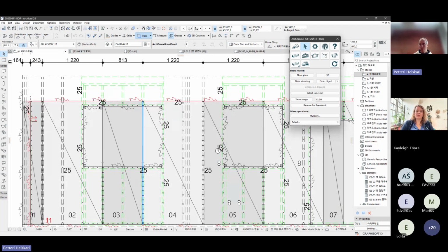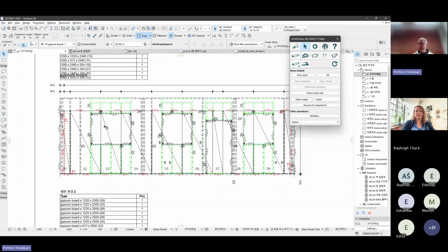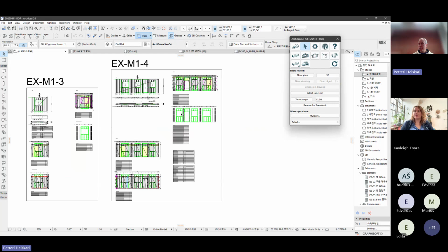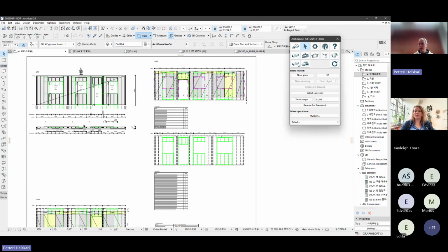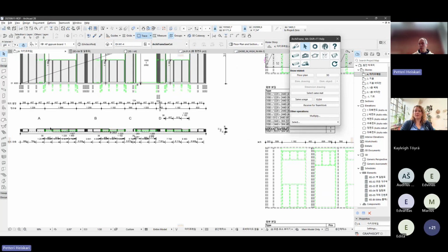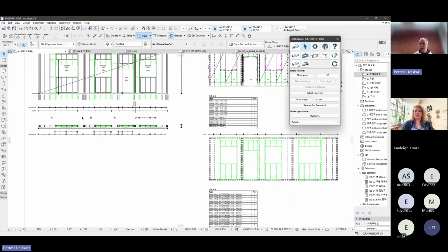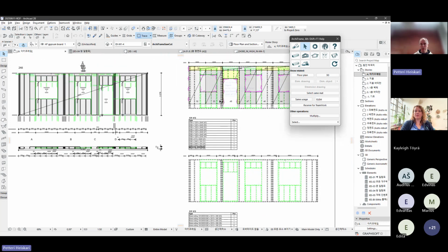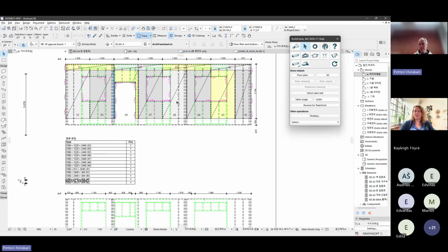So here you see some of the cuts, they have a depth of 25 millimeters to cut both boarding layers. Then this red one is cutting only the topmost boarding layer. Then here we have the view from both sides. So they install all electricity inside the wall. They also install the inside walls. So they turn the element and then it goes to the next framing station to do the inside boarding.